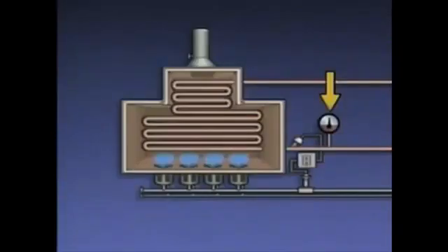Now, if the outlet temperature is too high, the temperature controller closes the fuel control valve slightly. The valve allows less fuel to flow to the burners, which causes the outlet temperature to drop back to where it should. When inspecting a furnace, look at the refractory.